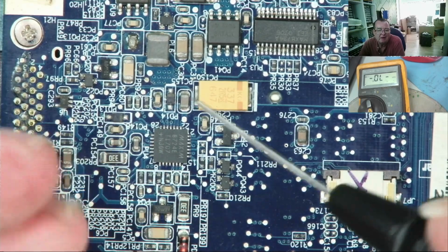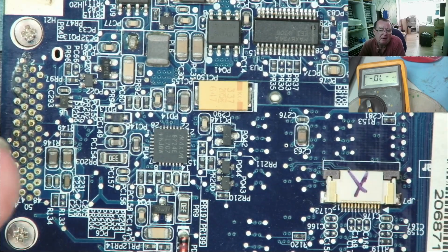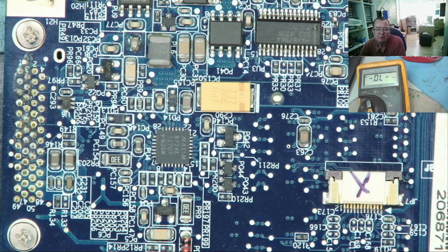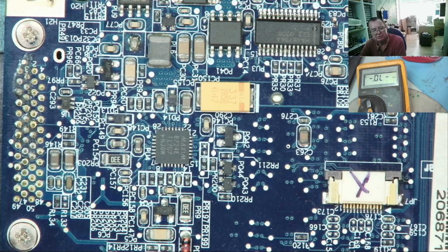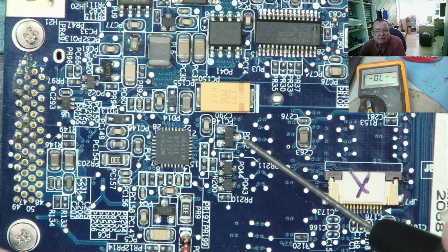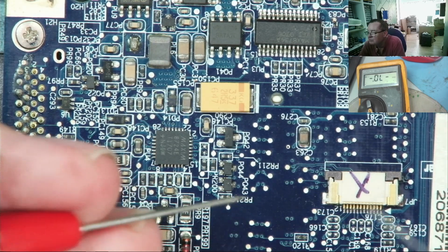So with a device like that, if I'm probing around, I can say it looks like a MOSFET. If I knew the drain and source, I could say P channel or N channel. To really test it, I would have to take it out of circuit, but it ain't short and it ain't open. So the chances are 90% or so that is a good MOSFET. So look at the next one.